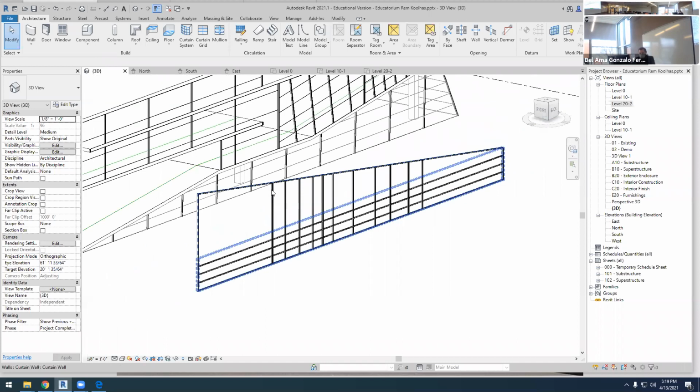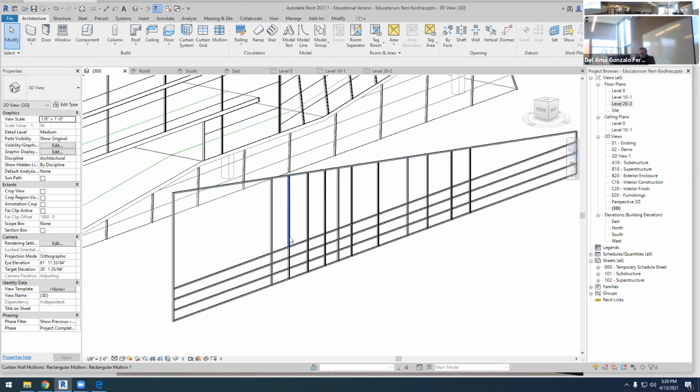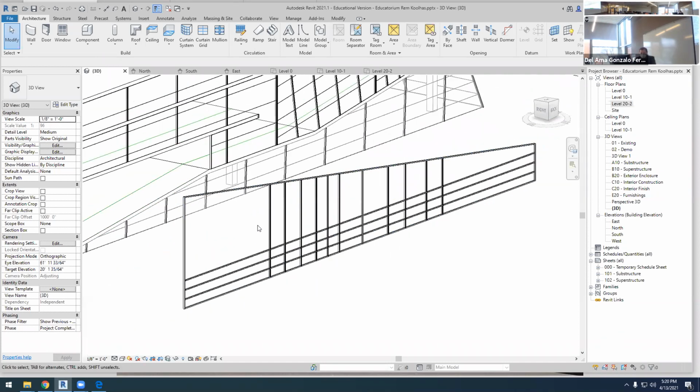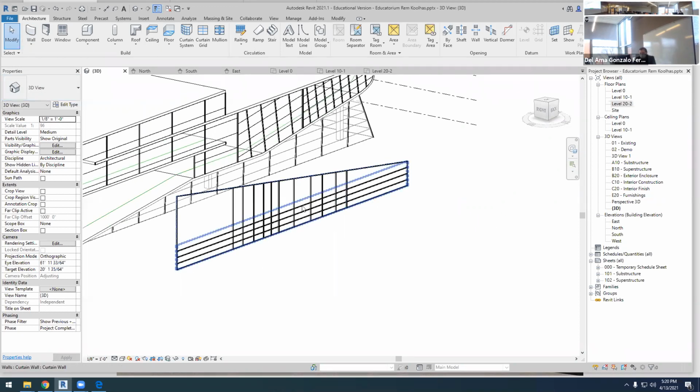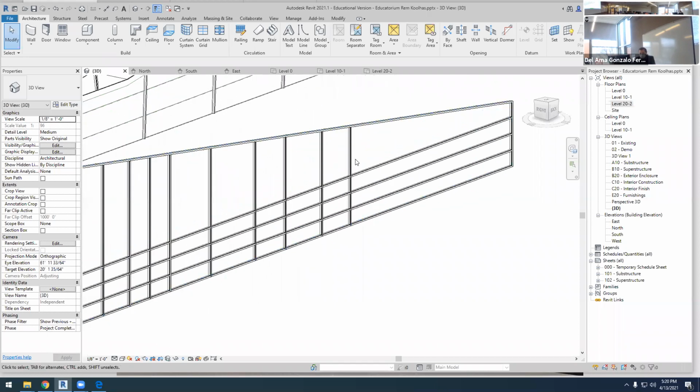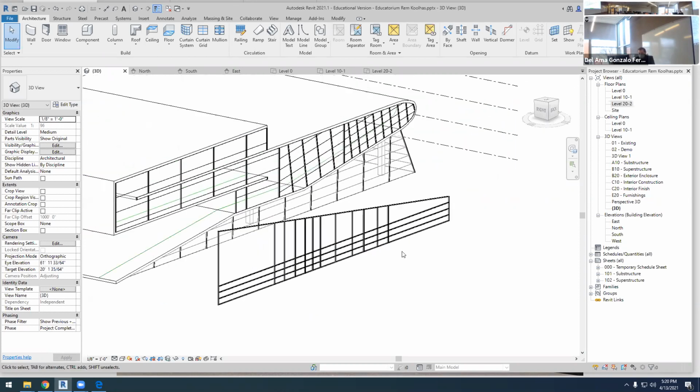It can be this with mullions and transoms, it can be the spider. But please, when you are working with curtain walls, do not use just this glass and that's it, because this is not feasible at all. We need partitions, and partitions make the project better. It's not something that is spoiling your project. On the contrary, if you create partitions, it looks better.